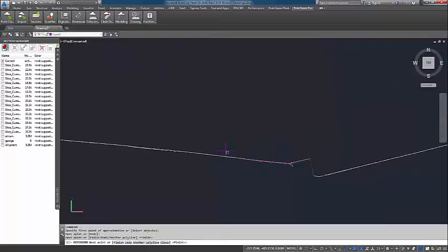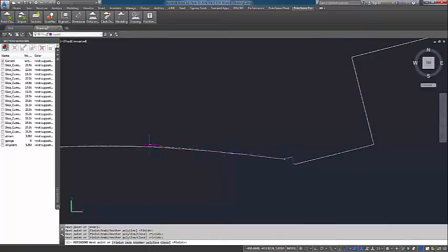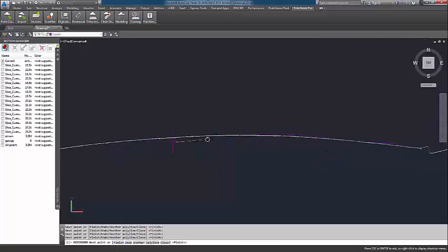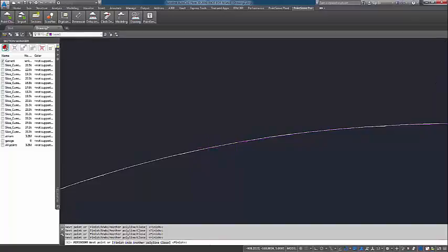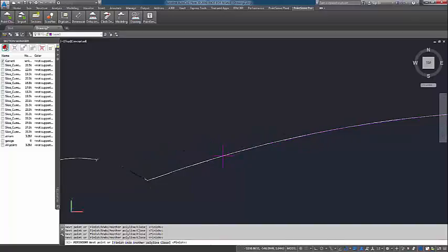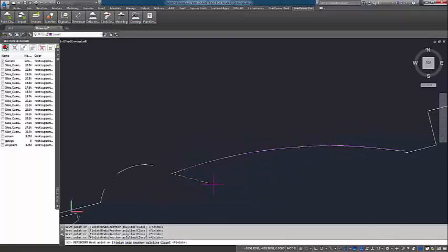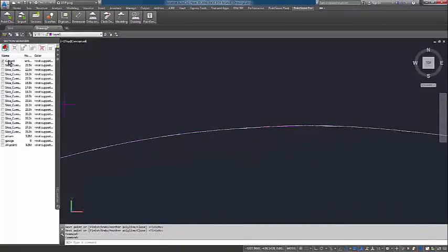Very similar to the Fit Outline Plan, we just trace, picking points. As many points as you'd like. The more points that you pick with this tool, the better it will adhere to the cloud. We do have a tool that can add points afterwards for editing if you like. When you get to the other end, just hit enter, and even in that area on the right there where I didn't pick the best point, you'll see that it does adhere to the cloud well.